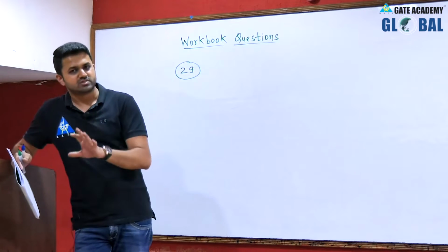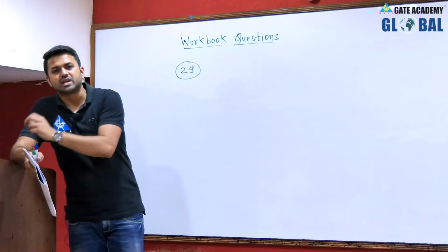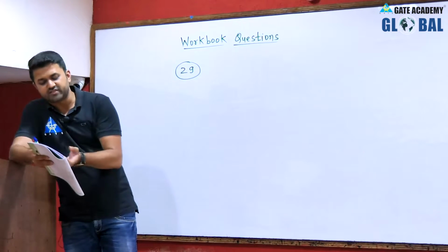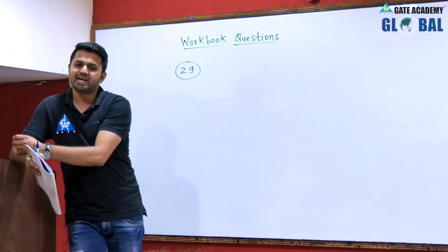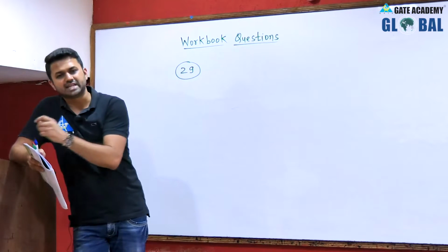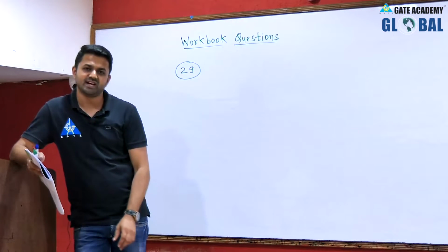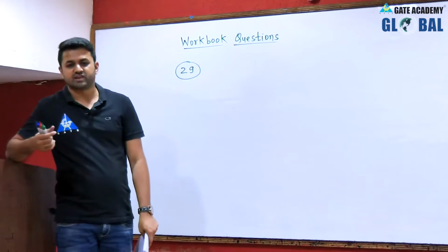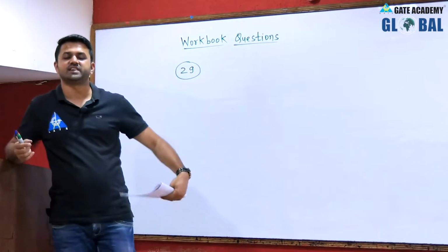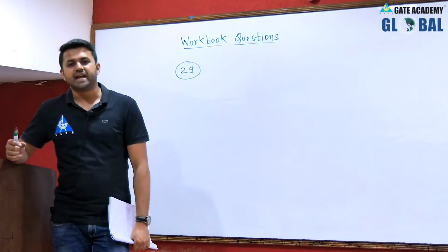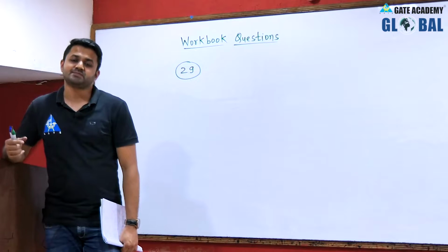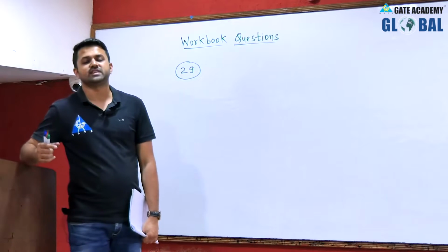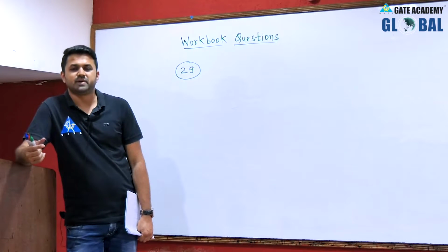Clear? You can also analyze whatever condition is given to us. You directly write c(t) plus m(t) and apply it to the nonlinear device, and you will get some output v0(t) which will have frequency components. You draw the Fourier transform of that particular v0(t), and then you see what frequency components pass through the band pass filter when we pass it through.